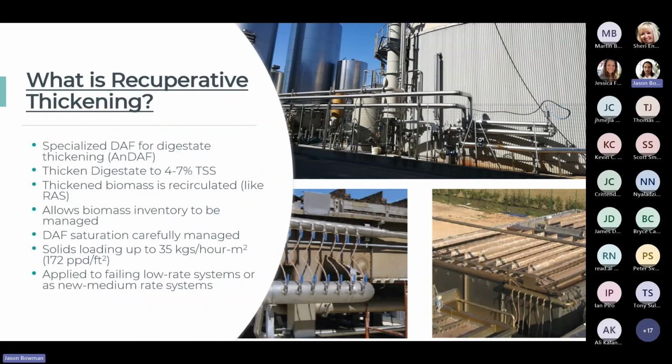One of the common issues with classical digester systems is that VFAs can build up too quickly sometimes. Digestion is a 4-step process in terms of how the bacteria react. Step 3 in that 4-step process occurs more rapidly than step 4, that is, the methanogenic bacteria can't really keep up, and this is what causes an imbalance in a lot of these digester systems. There are many more issues, and we'll cover those, but the point is, by having control over the biomass inventory, it frees up the flexibility, and we can better manage the buildup of VFAs and how the digester itself is operating.